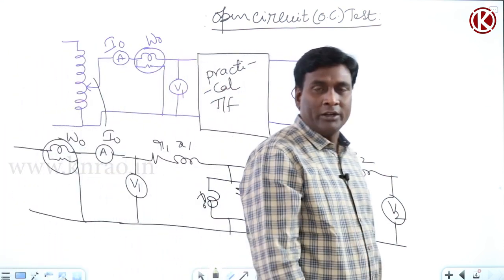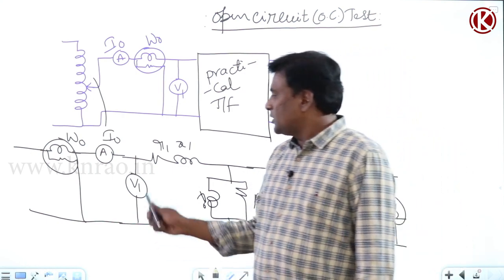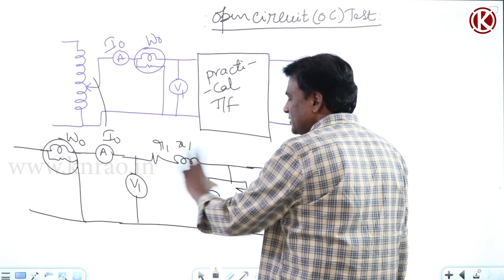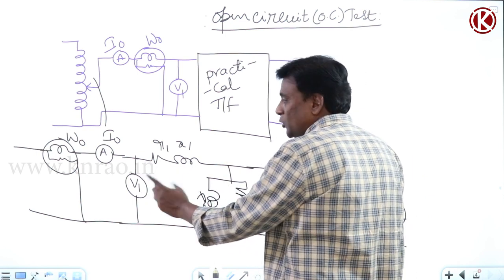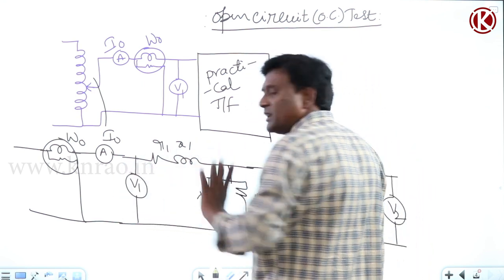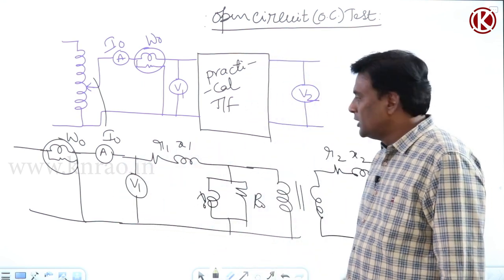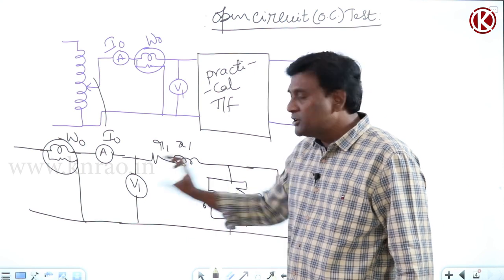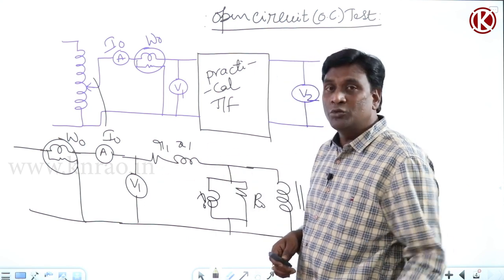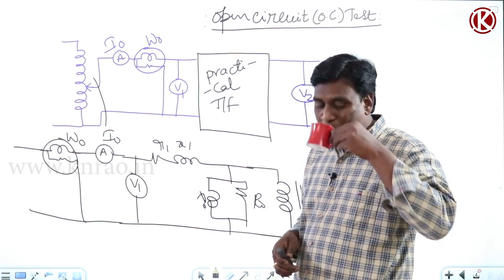That is one thing. The second thing is, if you think of the voltmeter, my voltmeter will record the voltage across this plus the voltage across this, right? It records the voltage across the series branch plus the voltage across the shunt branch. So if I shift the shunt branch from here to here, under that condition there will be no current flowing through the series branch.